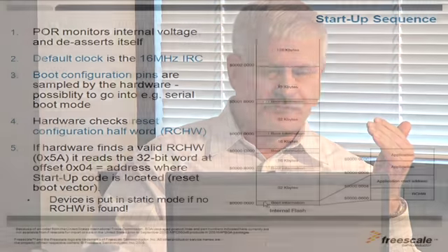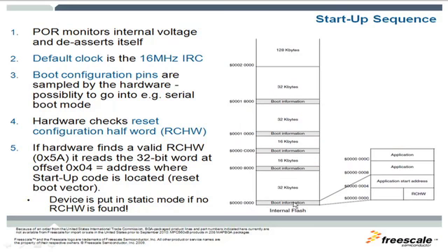And all our startup files, after this 5A, will do the second piece of required information for the boot configuration, which is to specify the start vector of code. So it's basically a constant for underscore start. So the first 2 words here are going to be this boot configuration ID of a 5A somewhere in this first word, and the second word will be the address of your start vector.